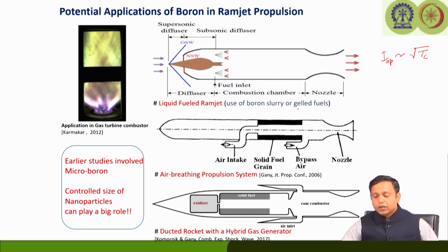Now, here I have written gelled just because in the case of slurry, the major problem is sedimentation, because you are mixing solid particles into a liquid. So, you have the liquid, and now let us say you are just adding some solid particles to it. How can you suspend these particles for a longer duration, because we are talking about something around 20 to 30% or even more loading into the liquid fuel? So, at some point of time, what is going to happen is that you will have an almost clear liquid, and all the particles will be settled at the bottom of this beaker or the fuel tank.